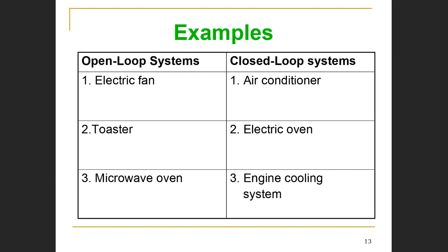The microwave also is an open loop system. You place your frozen meat in there if you wish, and you press defrost. It doesn't mean the thing is going to defrost. It will turn off in some instances before it defrosts, or in some it might start heating up the product to a point beyond which you intend. The point is that there's no measurement of the control variable.